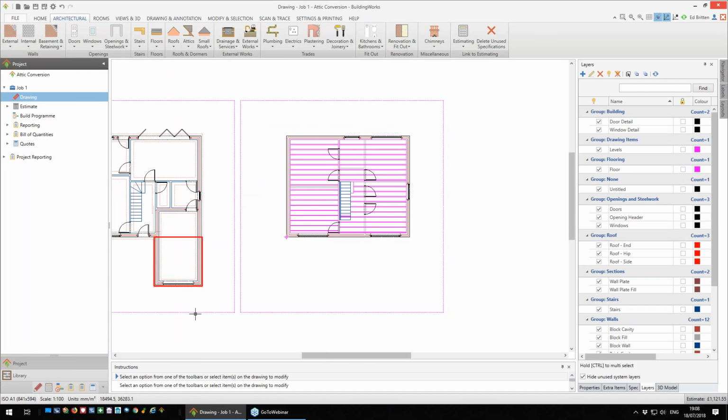So I've got a ground floor level, and I've got a first floor level, which is building up my 3D. I now need to make an attic level, because when you draw an attic, you don't draw it on top of one of the existing levels, because if you do that, if you draw, say, an upstand or stud wall upstairs, it will actually project down to the bottom of the level below. So if I did draw an attic roof on here and put an upstand on, that upstand would probably be 3 meters high instead of being, say, 1 meter high or something like that,